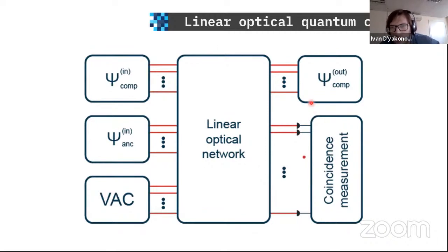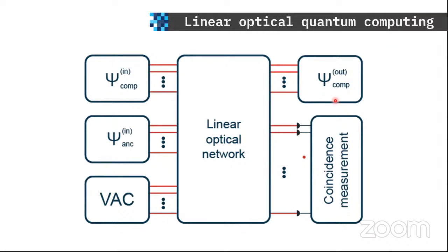Storing the optical state for a microsecond, I think, is almost an impossible task. Because, as you know, 1 nanosecond is somewhere around 30 centimeters, so a microsecond would be around several hundreds of meters probably, which is impossible to fit onto the circuit, a delay line this long.